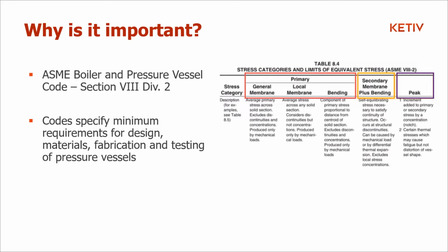You also have sections that are called design by rule or design by formulae. That's if you're using these rules directly, if you're using hand calcs, as Nigel mentioned, being his favorite part. If you're using that, you have separate codes for that. And if you're using FEA, then you have a design by analysis section, which is what we would be interested in.